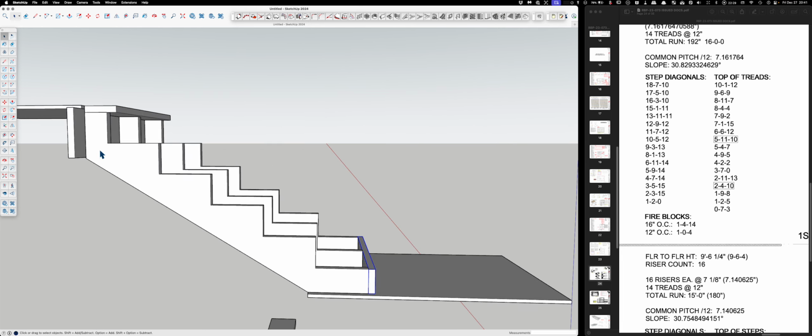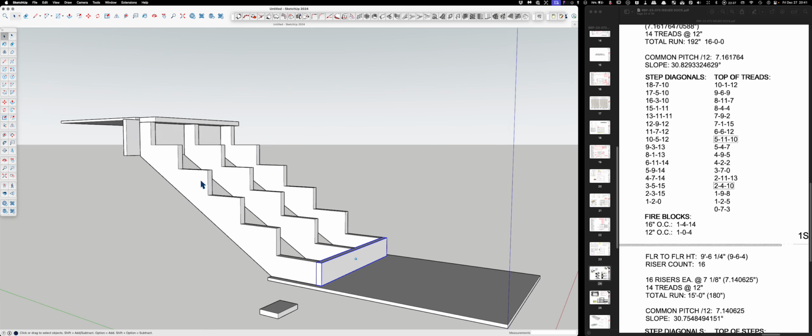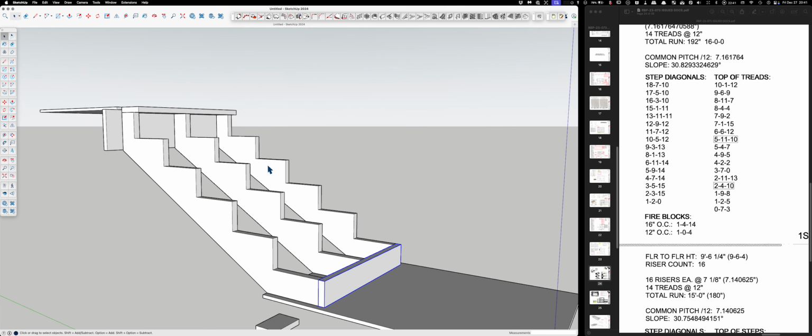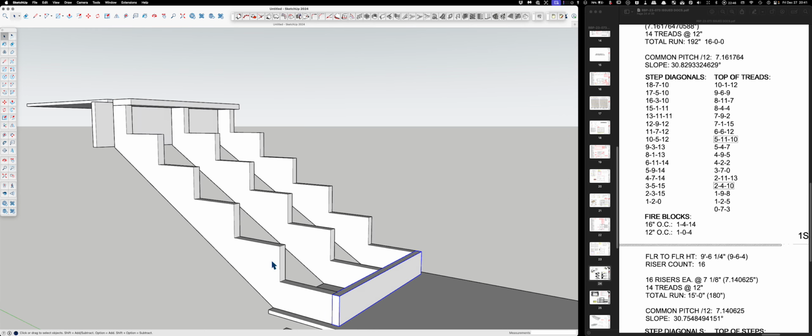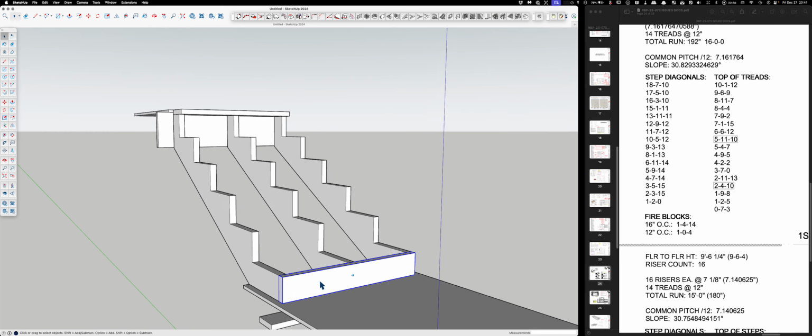And then I take the stringer and I glue it over to the spacing ledger and then shoot it on so nothing squeaks. And it's on. So these outer stringers are super strong. They're nailed to the wall every 16 inches vertically. So it's muy solid.